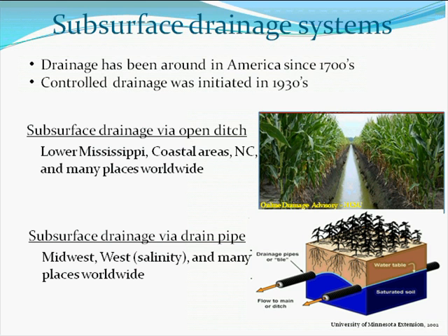I'd like to start here by talking about what is called subsurface drainage by open ditch. I have a drawing here. Anytime you have a shallow water table and any opening into that water table, the water is under positive pressure. Any opening, whether it's a ditch or an opening for a pipe, water will start flowing. So some of the early drainage systems were basically open ditch.